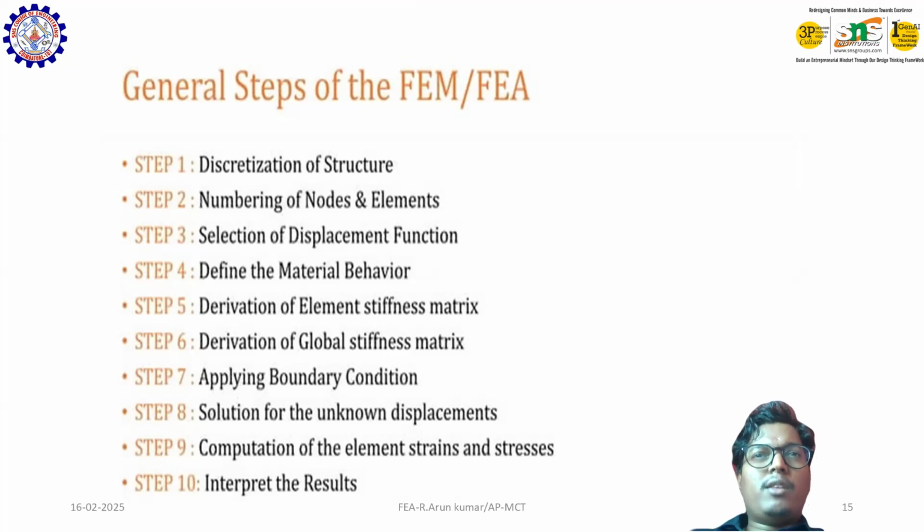element. So if I consider a rectangular bar and cut it into two equal parts, there are two bar elements, and each element has its own stiffness matrix. Based upon the stiffness matrices, you have to assemble them and substitute into the general matrix, and you get the unknown displacements. And also the derivation of the global stiffness matrix.